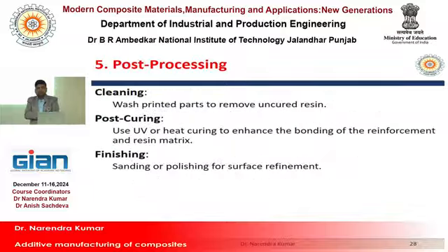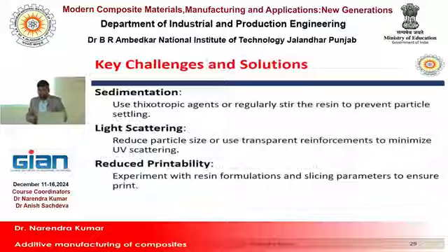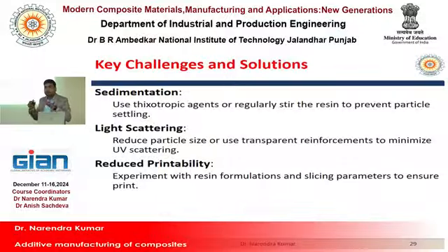Okay, I will provide these slides so you can go through them. One key challenge is sedimentation. Due to gravity, because here we use a tank, suppose you have prepared the composite by taking the resin and the reinforcement, but after a certain period of time, what will happen? The reinforcement fillers may settle down on the base.